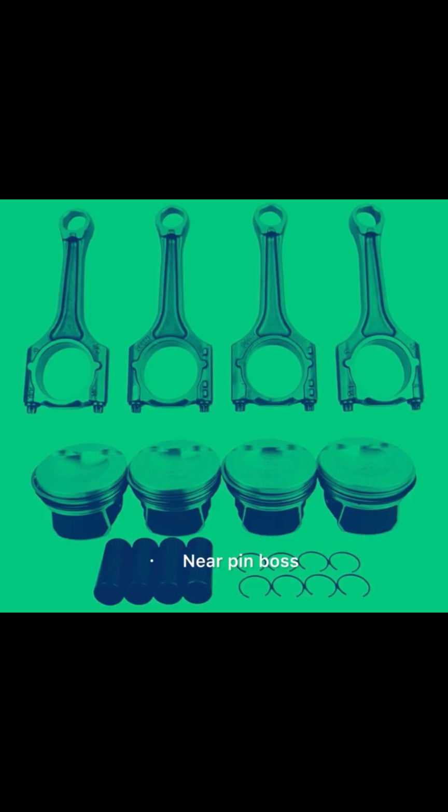13. How are piston rings indexed? Marking on one face of the ring to locate up position. Note ring type in each position. Align gaps as per instructions.